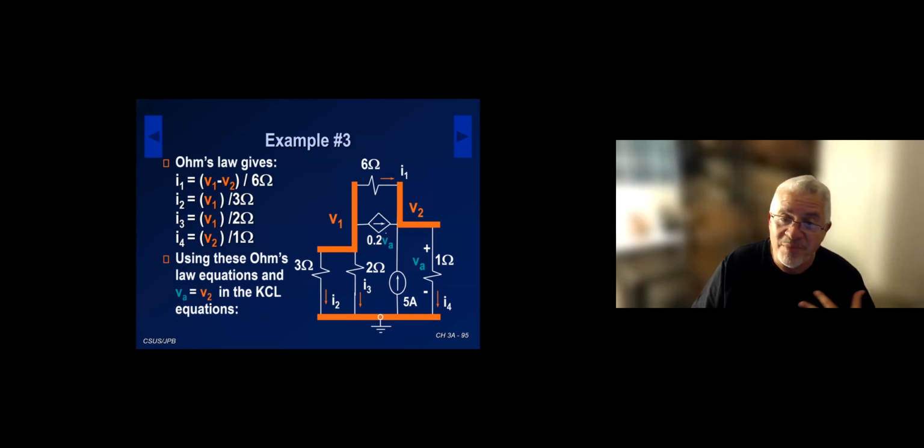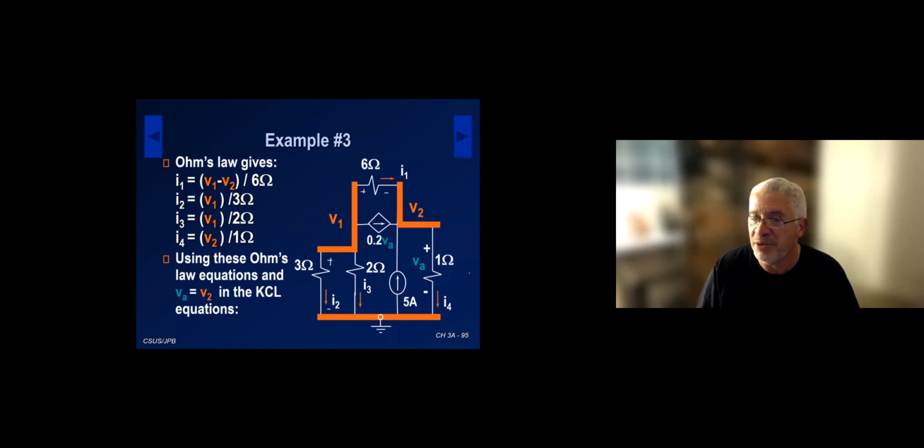So just be mindful here. When I put the current like I1 going from left to right, in my mind, I should see the plus and the minus here. For I2, the plus should be here and the minus here so that the current enters the positive terminal and so forth. So you should know that once you put the direction of the current on a passive element, that determines where your voltage is on that element.